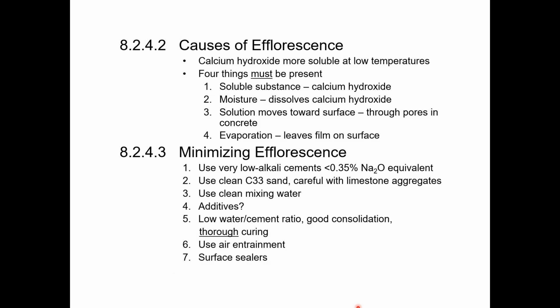So it's one of these problems where efflorescence doesn't necessarily represent a structural issue, where it's going to affect capacity or life safety. It doesn't look great, but if it's on the side of a bridge girder, do you really care that much? If it's on an architectural panel, you may have a bigger problem. So you want to make sure you know what the requirements are, know some things you can do to minimize it, especially if the area you live in lends itself to causing this.